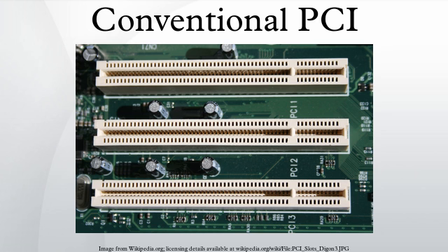Dual cycle address. To allow 64-bit addressing, a master will present the address over 2 consecutive cycles. First, it sends the low-order address bits with a special dual cycle address command on the CBE[3:0]. On the following cycle, it sends the high-order address bits and the actual command. Dual address cycles are forbidden if the high-order address bits are 0, so devices which do not support 64-bit addressing can simply not respond to dual cycle commands.